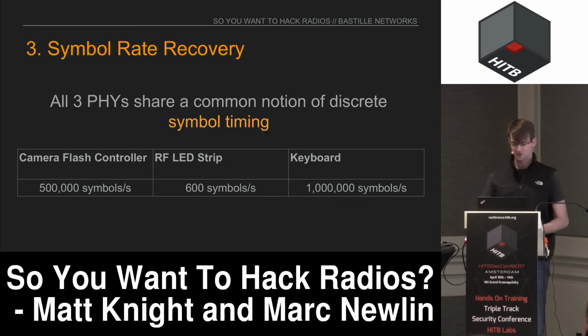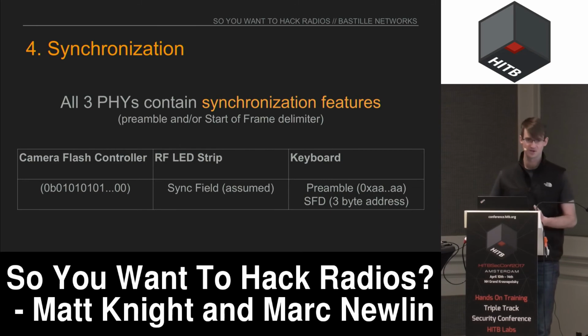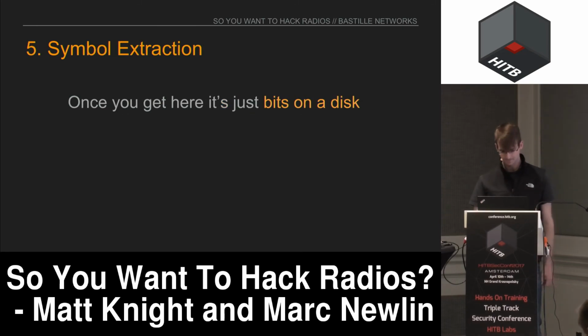All 3 PHYs share this common notion of discrete symbol timing. And again, we can rely on open source intelligence to discover that as well, and when that fails, we can discover it empirically. All 3 PHYs contain synchronization features, being a preamble and a start of frame delimiter. Although they look different for each PHY, they're all there. You know what to look for, and then you can leverage them all the same way to aid in the process of framing and decoding your data.